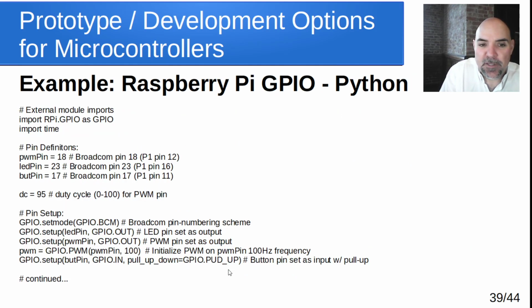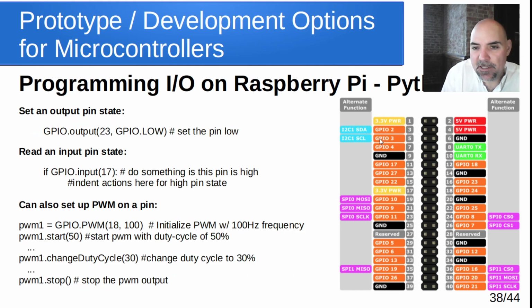And to show you where those pins would be for the I2C and SPI, here's the I2C pins. Down here, there's two SPI ports, SPI 0, SPI 1. Those are in purple here for the SPI, this cyan color for the I2C. And it actually turns out that there are other I2C and other SPI interfaces as well on here, but you have to enable those. So I'll let you worry about that or figure that out on your own.